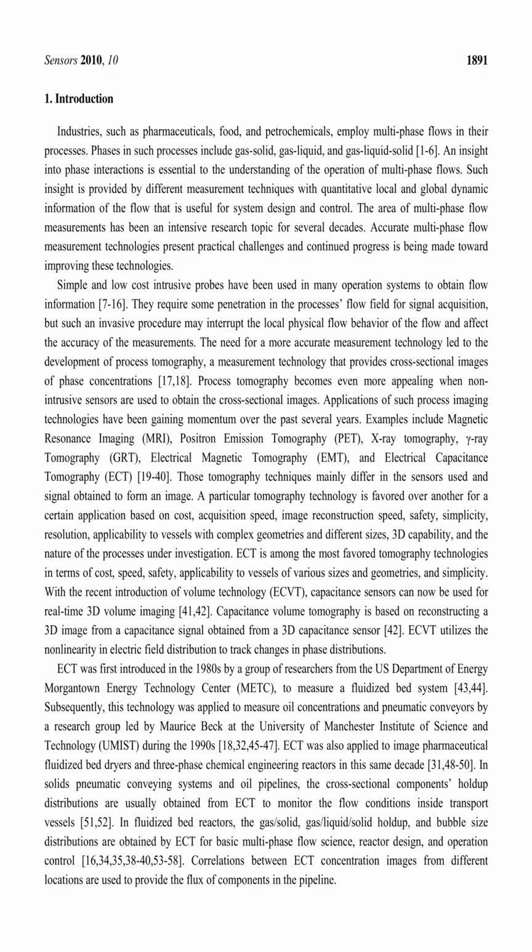Those tomography techniques mainly differ in the sensors used and the signal obtained to form an image. A particular tomography technology is favored over another for certain applications based on cost, acquisition speed, image reconstruction speed, safety, simplicity, resolution, applicability to vessels with complex geometries and different sizes, 3D capability, and the nature of the processes under investigation. ECT is among the most favored tomography technologies in terms of cost, speed, safety, applicability to vessels of various sizes and geometries, and simplicity.